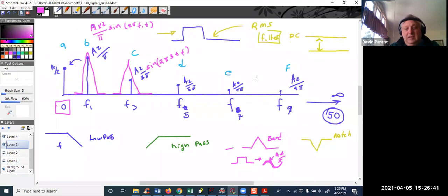All right. And like Jeffrey had mentioned, yeah, I would try to use a low pass. And you see how I'm drawing it where it goes straight up and down? The name for that is brick wall, right? Meaning you just want that and you want nothing else. The thing is there's no such thing as a brick wall filter that you can actually make, but you can keep trying to make it sharper and sharper and sharper, right?